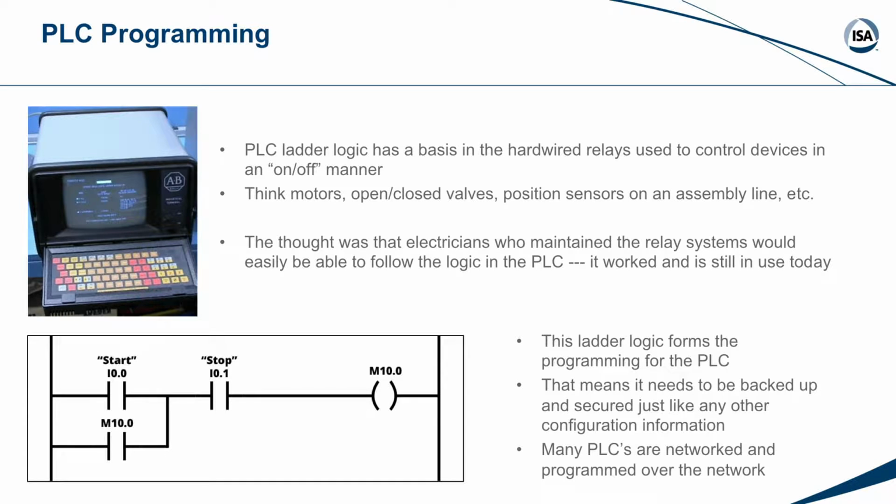That was so that the electricians in these factories, who were used to having a whole board full of electromechanical relays to build your logic, could follow it. A push button here goes to the coil of the relay, it closes the relay to energize the pump, the motor that's on the pump. You could wire your interlocks in, but if you wanted to change your logic, you had to physically change the wiring in those relays.